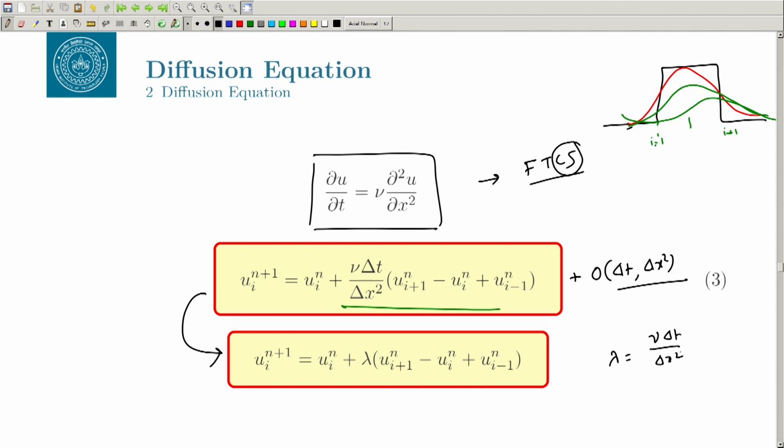Okay. So, now your diffusion will depend on your delta t, delta x, and what is your diffusion coefficient. In the fluid dynamics case, this is with the viscosity. If you are using the thermal problem, this will be the thermal conductivity K delta t del 2 T by del x square, right. So, this lambda needs to be basically honored even in this case.